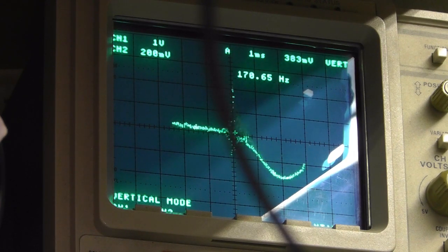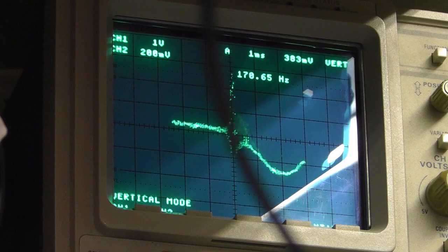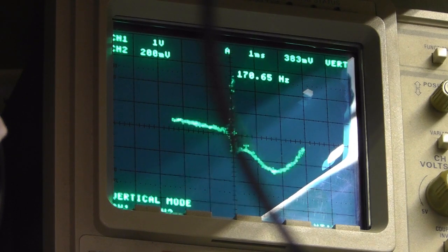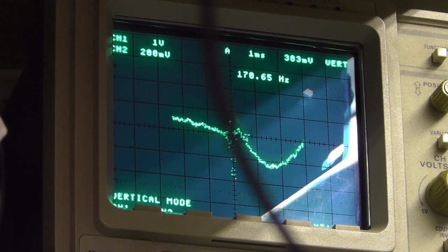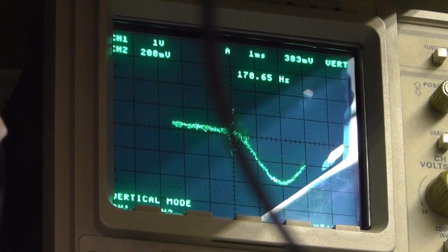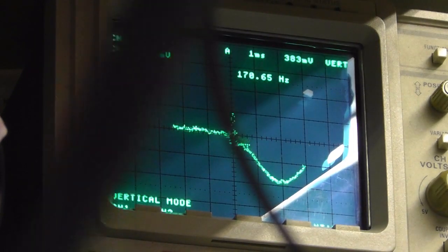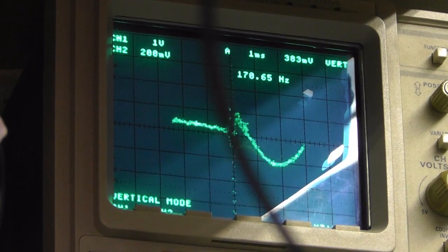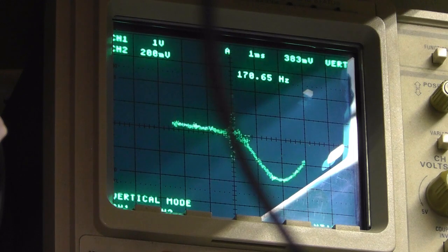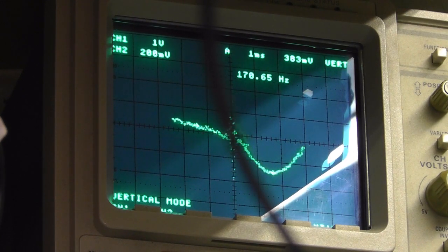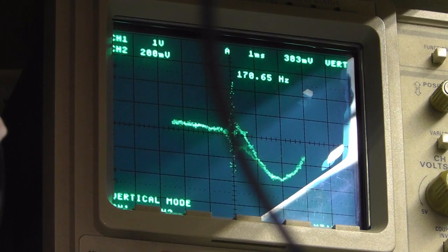Okay, so that's a bit more volume. So I'm going to adjust the first IF transformer. Okay, you see that marker's quite strong. I can move the marker generator away slightly, so it doesn't interfere so much. Just slightly away. There we go. Reduce the marker slightly. So we're adjusting the first transformer. Now this is basically a bit of twiddling around to get this right.